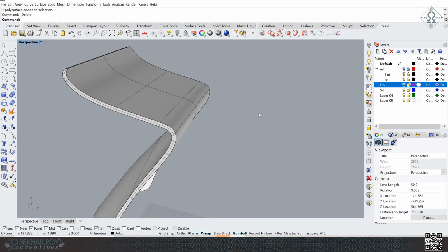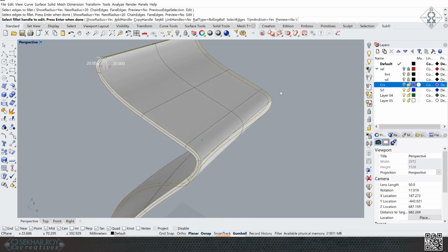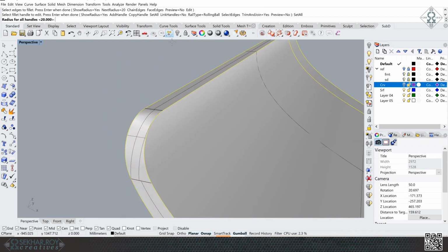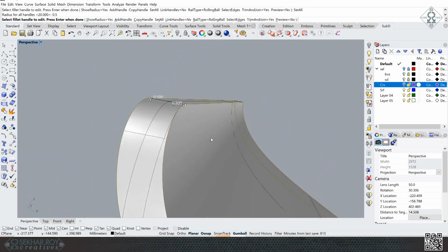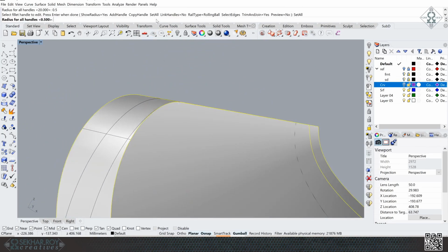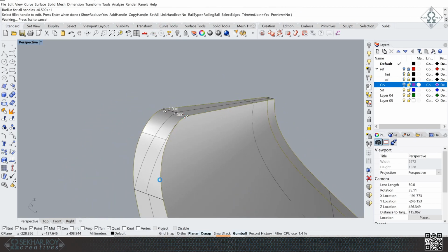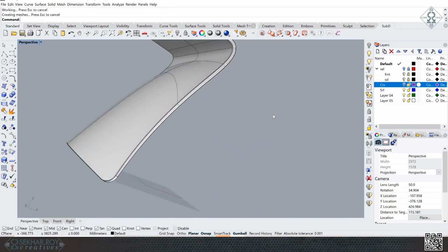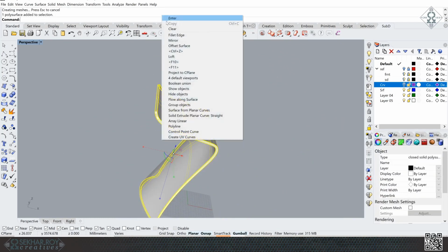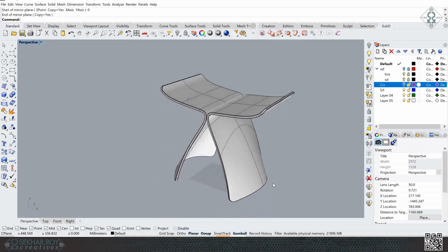I'm going to delete this piece, select this one only, do a fillet edge, do the fillet edge here, enter. I'm going to set this fillet radius set all back to maybe 0.5. I'm looking here at a very small radius. Okay, maybe 1, set all to 1. 1 also looks good, and press enter, and it will round up the entire sharp corner into this nice round corner fillet. And we can now take this and go to mirror and mirror it again from the center of the grid, and that completes our wooden geometry.